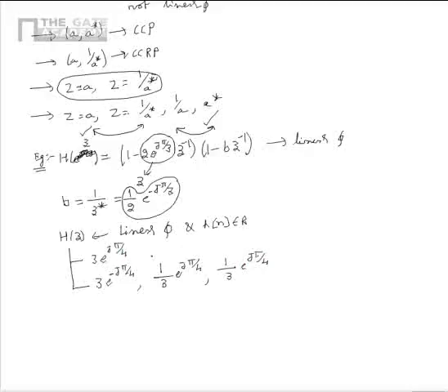So by using the property that the given system is linear phase and has real impulse response, the zeros are located at 3 e^(j pi by 4), 3 e^(minus j pi by 4), 1 by 3 e^(j pi by 4), and 1 by 3 e^(minus j pi by 4).